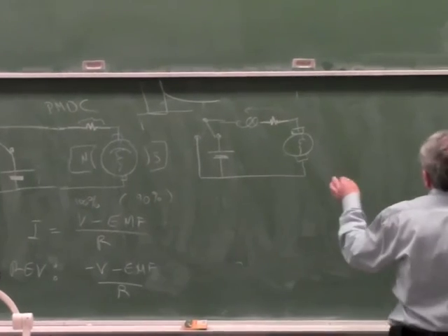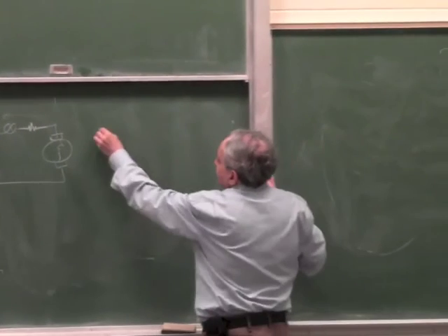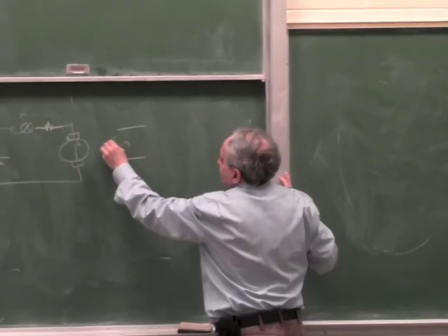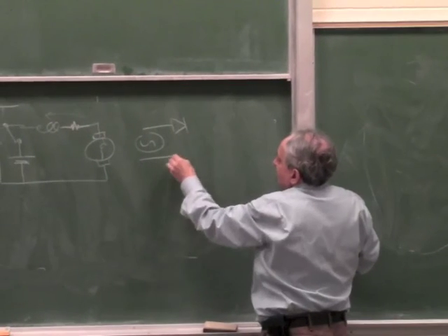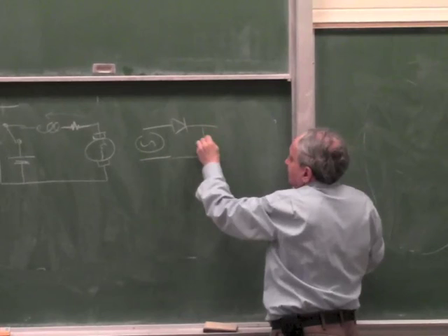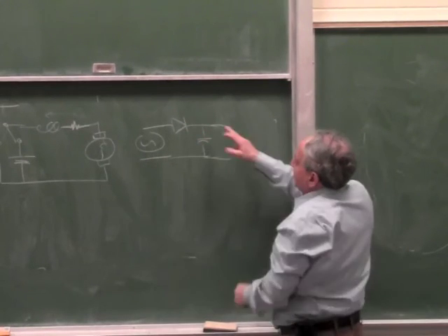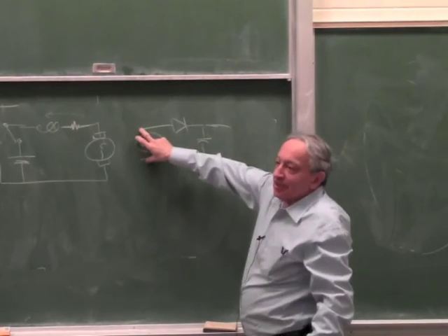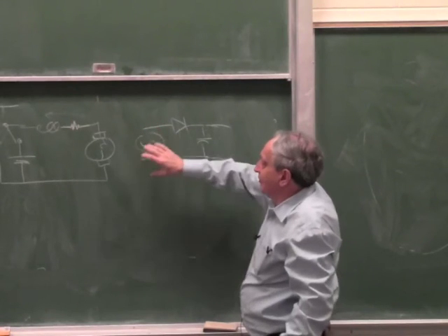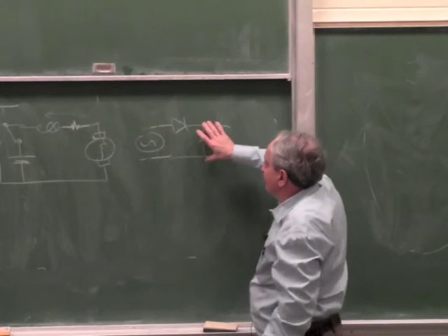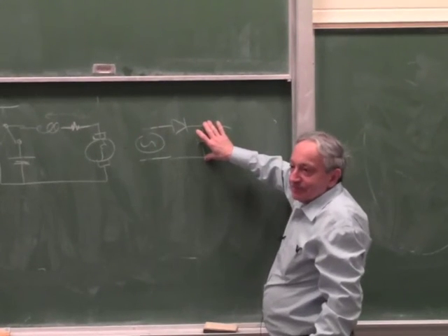So if you think of your computer power supply, it looks like this. The line comes in here, then it has a rectifier. It's actually a bridge rectifier, but symbolically, with a capacitor. So it makes a DC, and the DC depends on the input voltage. If you give it 100 volt input AC, what will be the DC voltage?